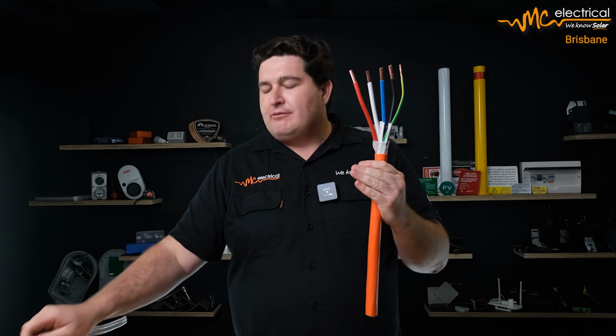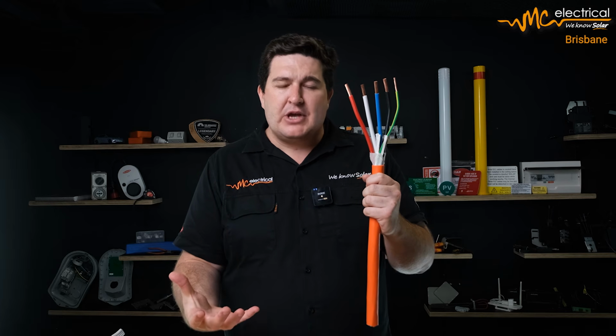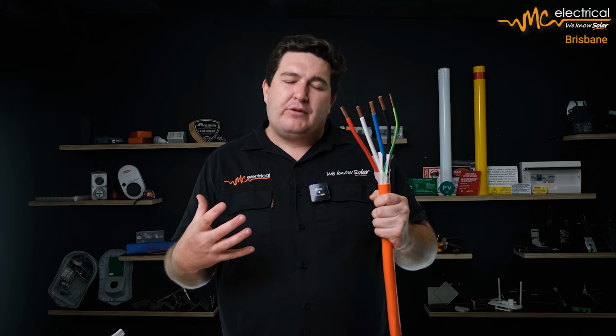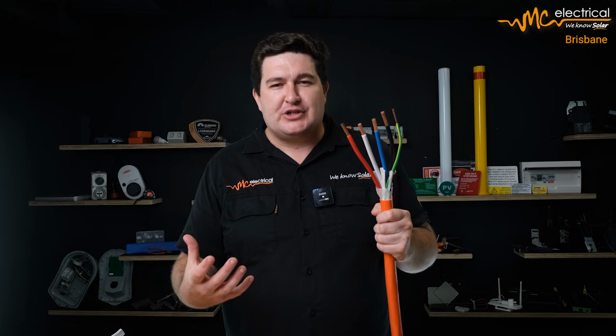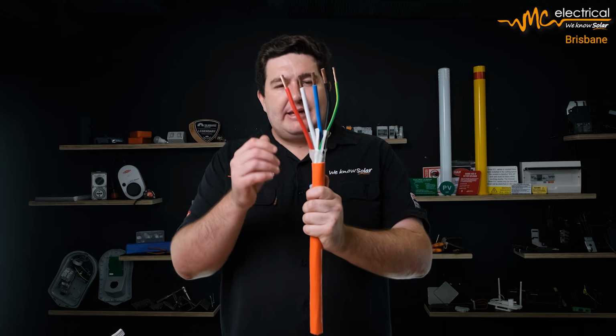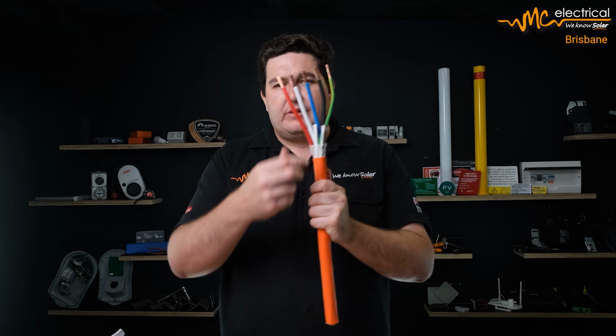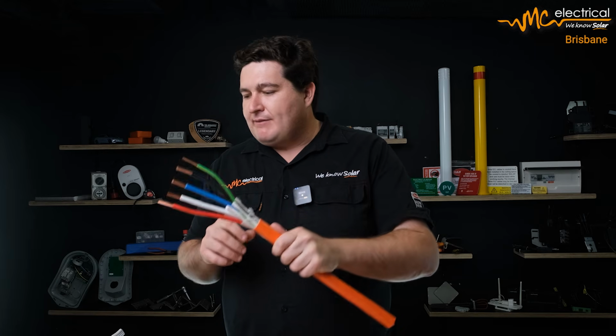on an engine. And the reason some homes will have three phase is either because they have high power loads, or they might have a big ducted aircon where they have a big motor. So often for electric motors, three phase is much more efficient. Again, it's like having three cylinders on an engine. So on a three-phase connection, instead of three cables, we've got three actives, one neutral, and one earth. So 5 cables. So it's a much heavier duty connection.